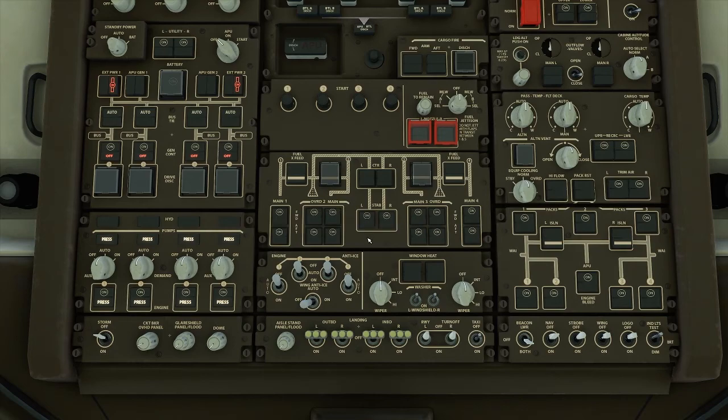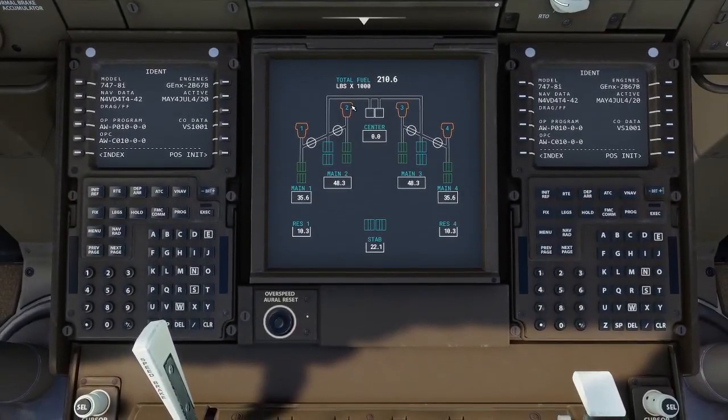And if we look at the ICAS, now you'll see that they've all changed colour. So the green ones are the standard pumps, and these blue ones are more overpowered than the rest of them. I think they were called override pumps or something like that. So they're basically, whenever they're on and you've got all your crossfeed valves open, which are these valves here, that means that these pumps will supply fuel to all the engines, all 4 engines.